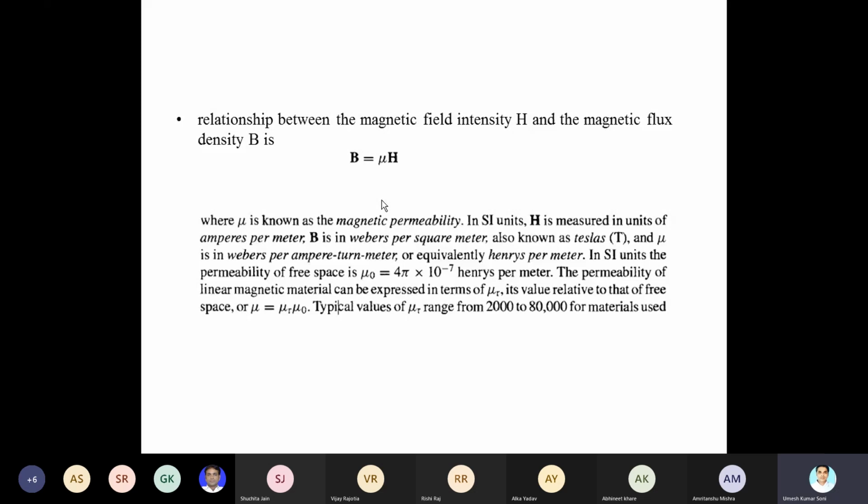तो परमेबिलिटी एक स्पेसिफिक होती है एंड परमियंस पूरे मटेरियल का होता है। रिलक्टेंस पूरे मटेरियल का होता है और रिलक्टिविटी स्पेसिफिक होती है। ऐसे ही रेजिस्टेंस पूरे मटेरियल का होता है एंड रेजिस्टिविटी इज स्पेसिफिक, कंडक्टिविटी इज स्पेसिफिक एंड कंडक्टेंस इज फॉर ओवरऑल लेंथ। ओके, तो ये हम नोट करके रख सकते हैं। म्यू 0 इज इक्वल टू 4π × 10⁻⁷ हेनरी पर मीटर।